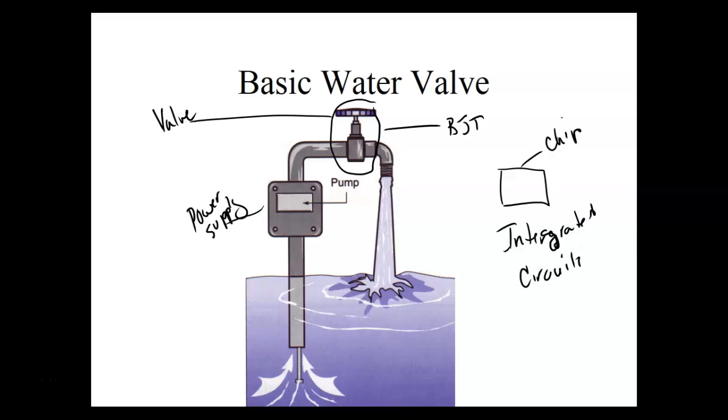If you tear a radio open, you're going to see a few resistors, but basically one chip, and then you'll see the power section too. Radios have been around a long time, and when something has been around that long, eventually, to reduce the cost, they start integrating most of the components onto a single chip. But it's still not going to do away with your power transistors. Those will probably still be mounted to the back of the radio, heat sinked back there.